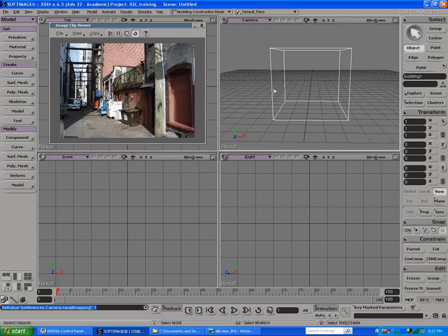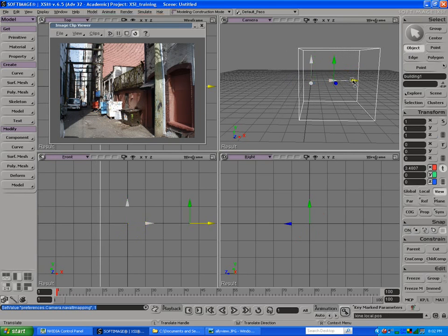Okay, so we have one cube. We also want to move the cube, so we have here the transformation tools. We have Translate, T, Rotate, R, and Scale. And the hotkeys for these are V to translate, C to rotate, you can see a little C here, and X to scale. The way I remember those is X is like two arrows going out, it's like scale. C is like a big round area, kind of like rotate, and V is to me like an arrow, so translate.